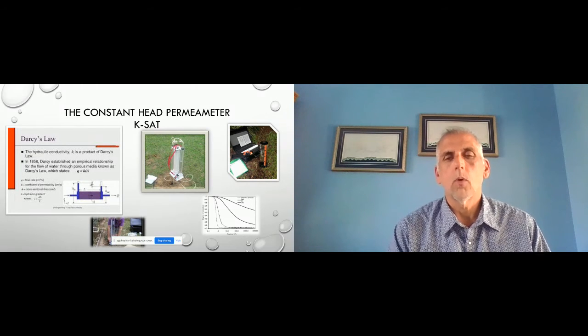What we're looking for is, once that soil column gets saturated, we want to know how much water is percolating into the soil at the saturation rate. And then we can use those numbers to try to confirm our long-term acceptance rate. We don't ever use the hydraulic conductivity to assign a long-term acceptance rate, but we do use it to confirm those.